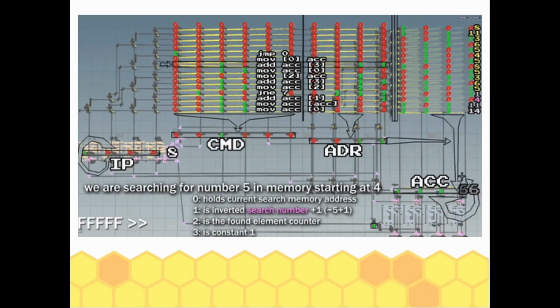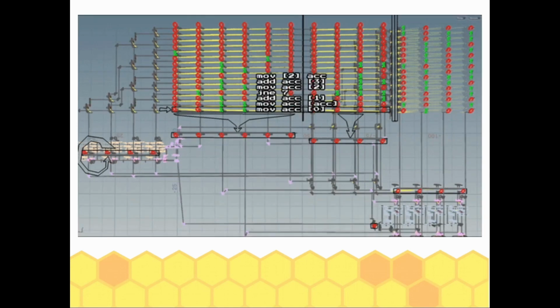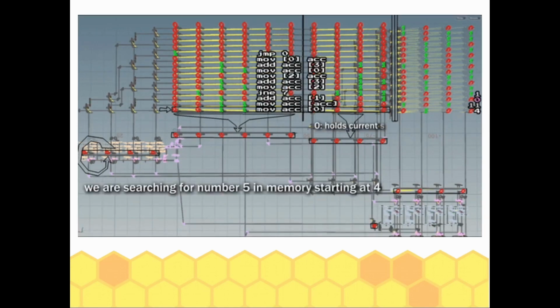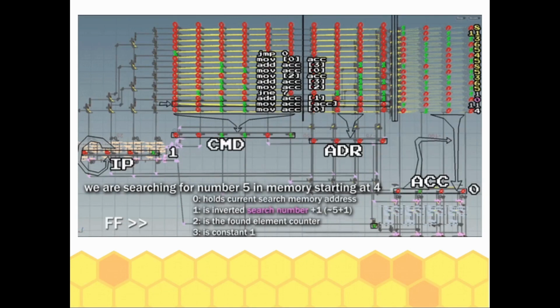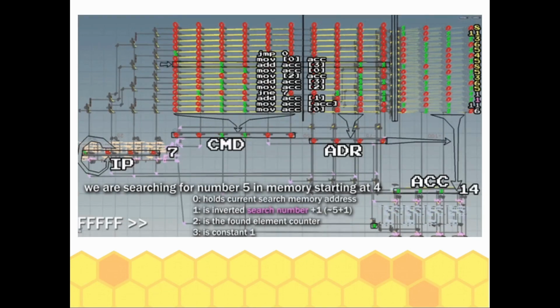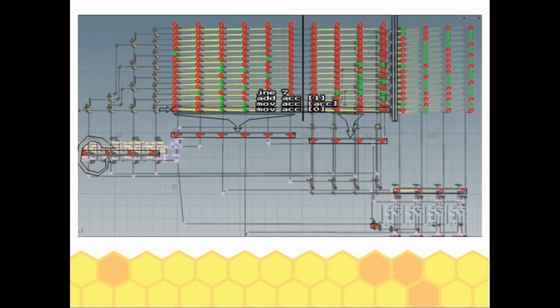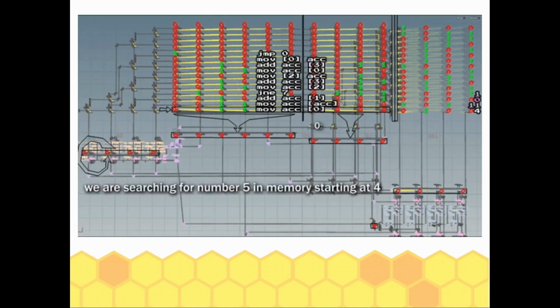Sorry, are they concave or convex, the cogwheels? Oh, of course, they're all convex. You mean that they are decomposed? Each tooth is different? Yes, they were originally created to be only convex shapes, because concave is a weird beast. I think the Bullet library itself works fine with concaves, but for some reason Houdini just cannot work with concave objects without decomposing them into convex ones.